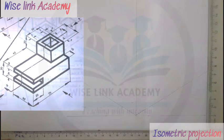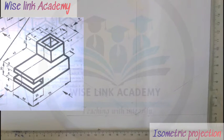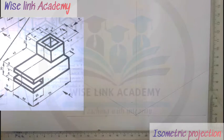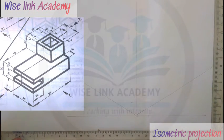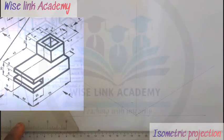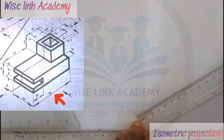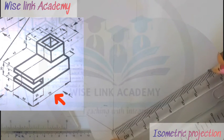Now, after you have successfully constructed your isometric axis, proceeding, I have successfully constructed my isometric axis. So what was my next task? Next task is to get the length, breadth, and height. Of course, my entire length from this figure here is going to be 75, as you can see my arrow indicating. So from here to here is 75, right?